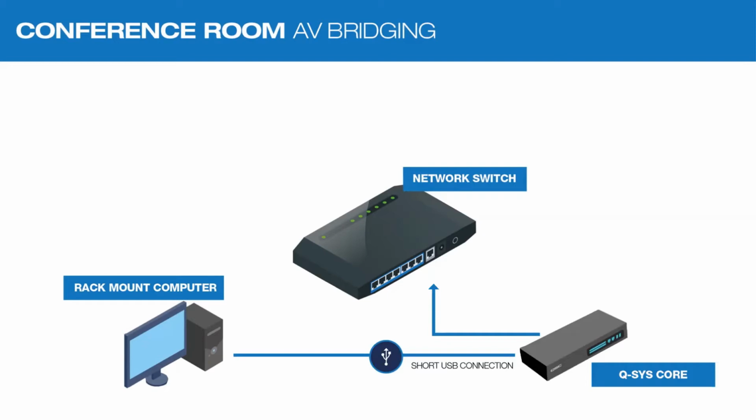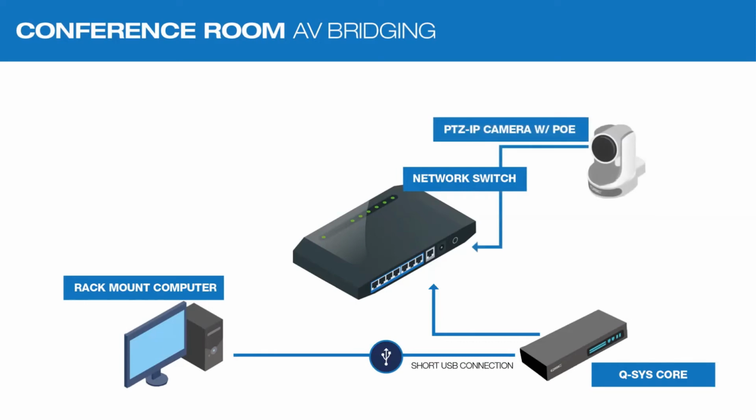The core will then present a driverless webcam to the PC and also an audio device. It will present itself as an echo cancelling USB speakerphone if it was chosen as such in the design, and then a USB webcam. Any audio in the Q-SYS environment can be presented to this PC. And also, if we add cameras, we can present any Q-SYS PTZ camera to the webcam feed.